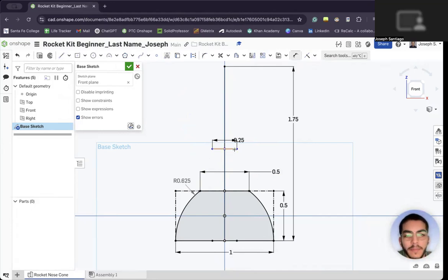Now, what we're going to do is dimension this. The dimension tool is one of the most important tools of the whole program. You can use it anywhere, everywhere. Now, to dimension this to this, and to do it 0.25. There we go. So you see it's 0.25 distance. You see there's a bunch of numbers here, a bunch of dimensions, things everywhere. So if you need to organize things a little bit, you totally can, to whatever works best for you, and